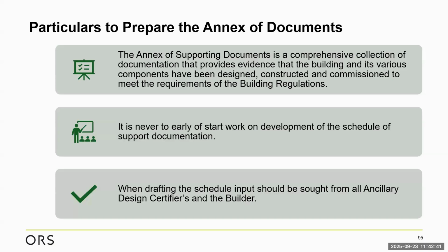We present it in front of the builder and say, look, this is what we see, the documentation that you guys have to provide. And a lot of that information can be testing and commissioning, it can be in relation to materials, the DOP and CE certs, it can be QA, QC documentation from the construction works, it can be technical submittal register, benchmark registers, the entire list of documentation that we'd like to see.